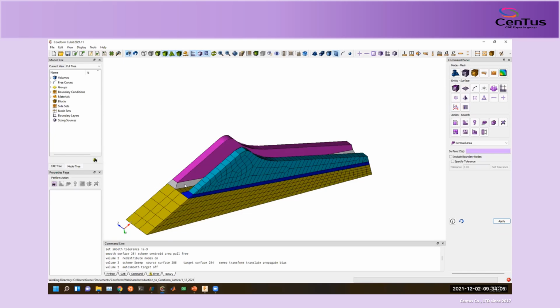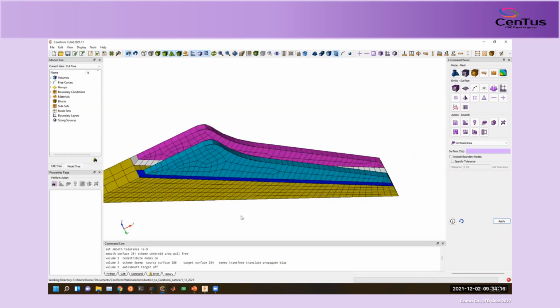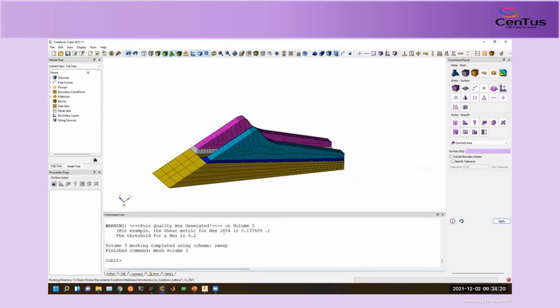As well as then these final two volumes on the other side. Once we've built our mesh layout, we can build a U-spline. Right now we build U-splines only through the command line. We don't have a GUI interface for it. We can set our U-spline degree and continuity and build it.